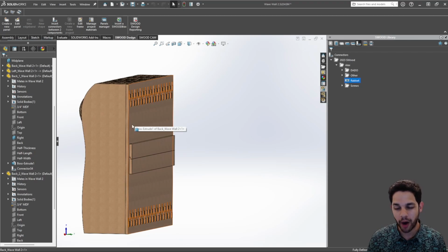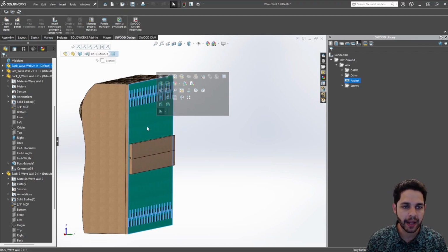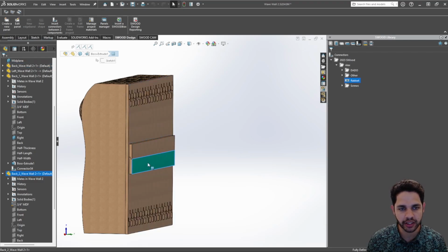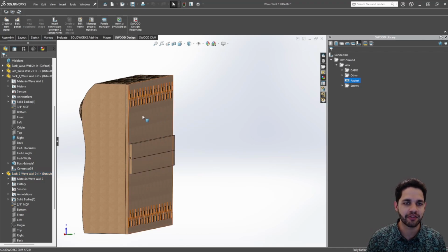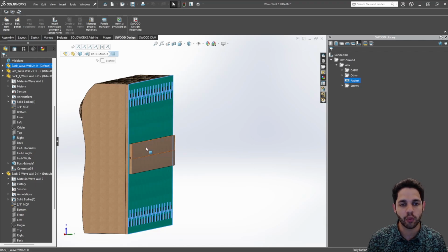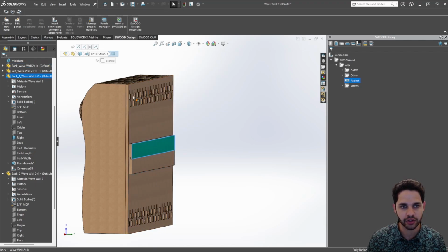And what I would probably do is install this back panel, well actually the stretcher first, or excuse me, I would install the French cleat, the one mounted to the wall, first, and then from there I would install the back panel with the stretchers attached to it, and then I would mount that onto the French cleats.